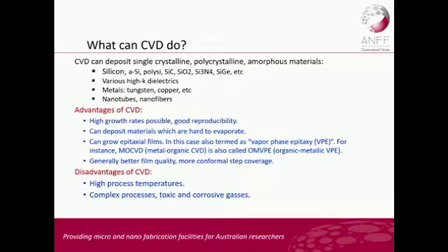The disadvantage of a CVD process is the temperature. Usually the process will be carried out at a high temperature. It depends on what kind of CVD process you're using. And they also use lots of toxic or corrosive gases.